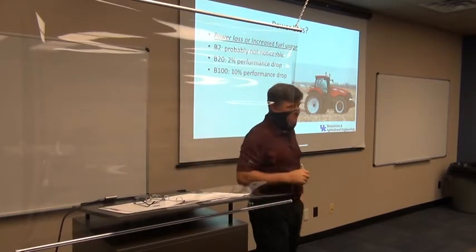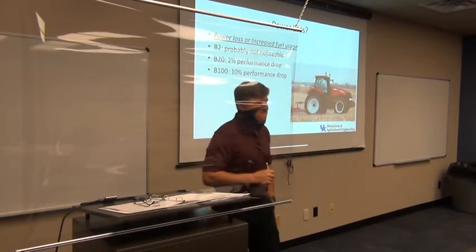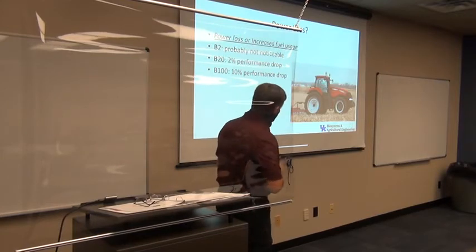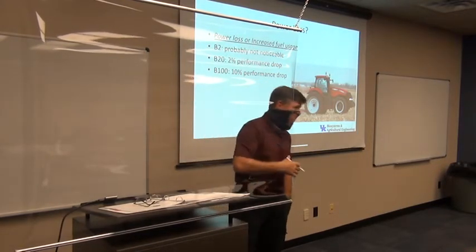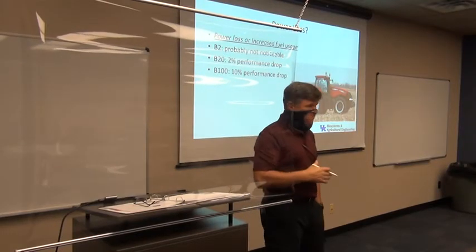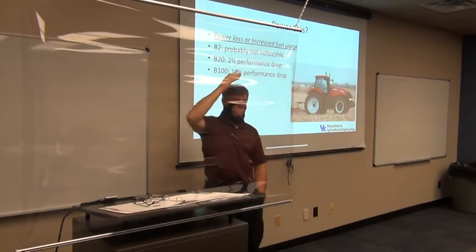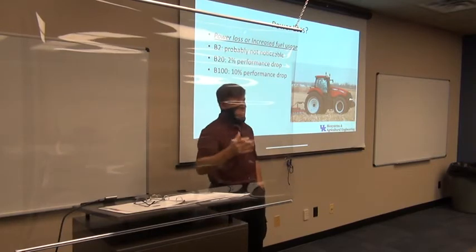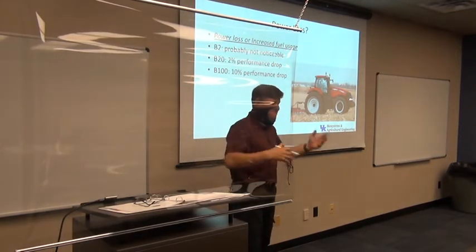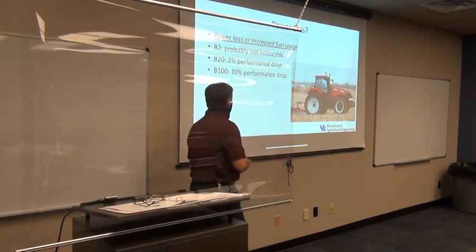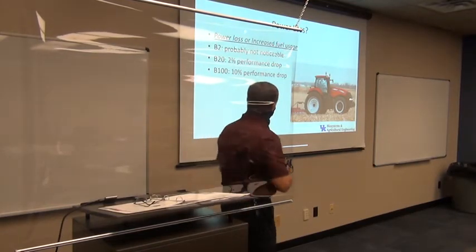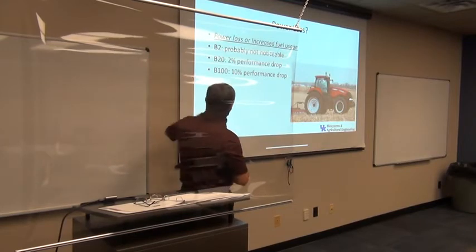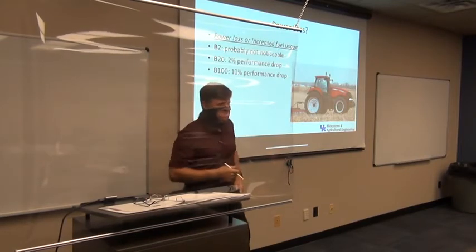So how much power loss am I going to see? I put this together for farmers who say, okay, I've got this tractor out here, and all these fuel suppliers, this was 5 or 10 years ago, are trying to sell me all this biodiesel. Is it going to hurt my tractor? Is it going to void the warranty? What's going on? So here's what we told them: with B2, it's probably not going to be noticeable. If you have B20, you're going to see about a 2% performance drop.